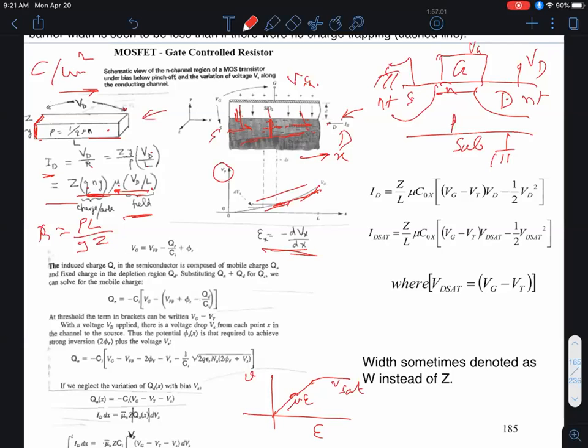Why? Well, N has units of number per centimeter cubed times y, which is in centimeters. That'll give you number of electrons per centimeter squared if I look at the resistor from the top, okay? So it's the electrons per unit area, integrating as a function of the depth of the resistor, okay? And then to get charge, you have to multiply by the charge of the electron, okay?